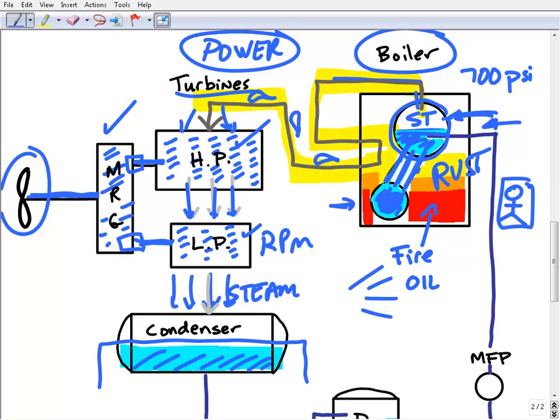And actually, that's happened where engineers, for one reason or another, lost their way on what the water specifications were in the boiler, and you can have oxidation going on, and you can rust out tubes. Rusting can occur, and we all know what happens when you think about aluminum or steel. When it rusts, it gets weak, and then eventually you have holes. And believe me, the last place you want to have any little pinholes or rusting or weaknesses is around something with 700 psi of steam. So very, very dangerous.